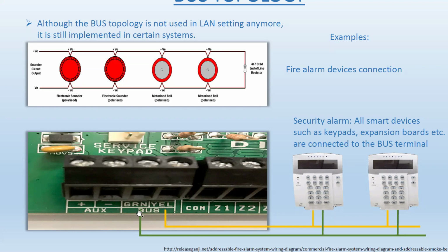Now, the wires that are used for the fire alarm and, for the most part, for the security alarm are so-called Z type wires, Z4. Z4 is a thin wire with 22 gauge solid conductors, and it has 4 conductors, usually yellow, green, black, and red.